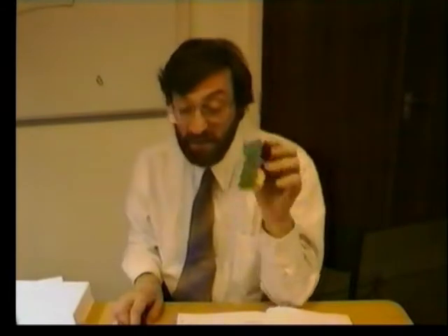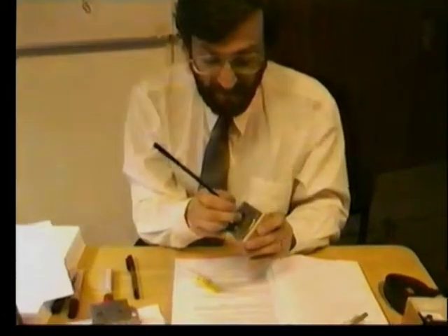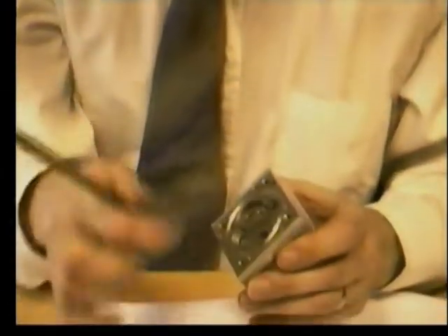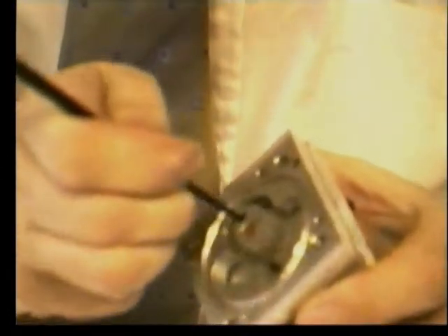This little particle device gave us a flow of current. The sensor wasn't an analog, wasn't a variable signal, it was either off or on. So it's a pulsed output, a frequency. This very expensive bulk flow sensor, £200 worth, gave us a frequency as well. As that rotated, we got a series of pulses flowing out.